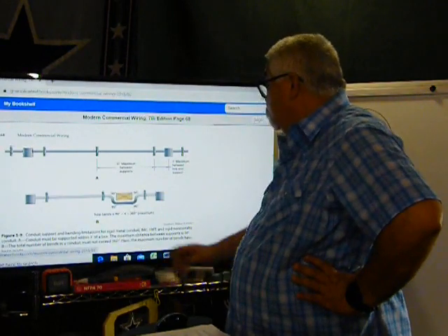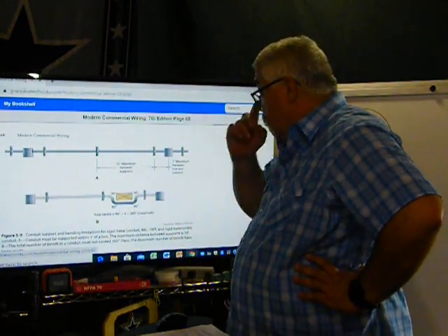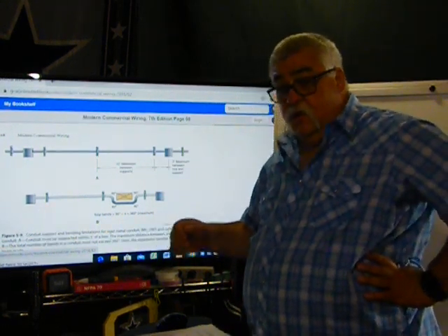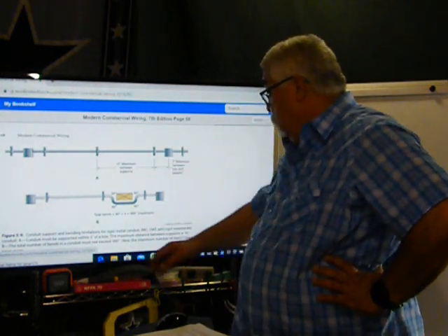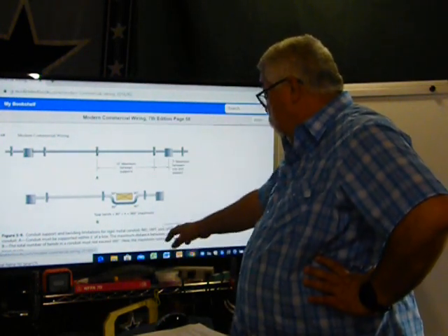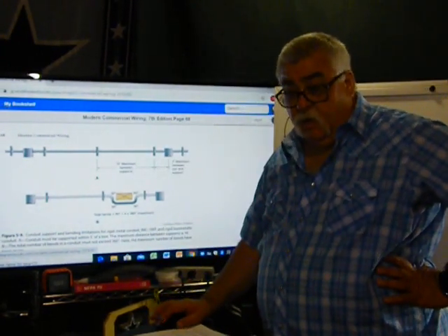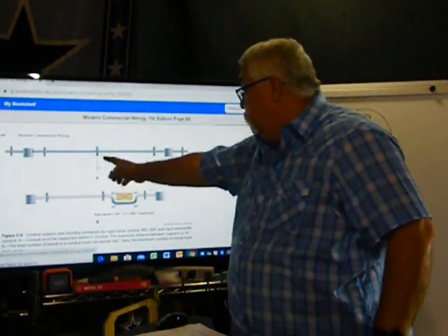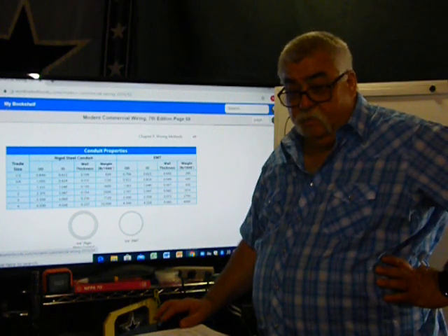Supporting your boxes. 3 feet from a box if you're using metal conduit. 3 feet from a box if you're using PVC, ENT, flex, or anything that changes. But for most parts, rigid metal conduit, IMC, and EMT, 3 feet from the box and every 10 feet after. Rigid metal conduit, once you start getting into the bigger sizes, your gap can increase. Even though it can, I never do.